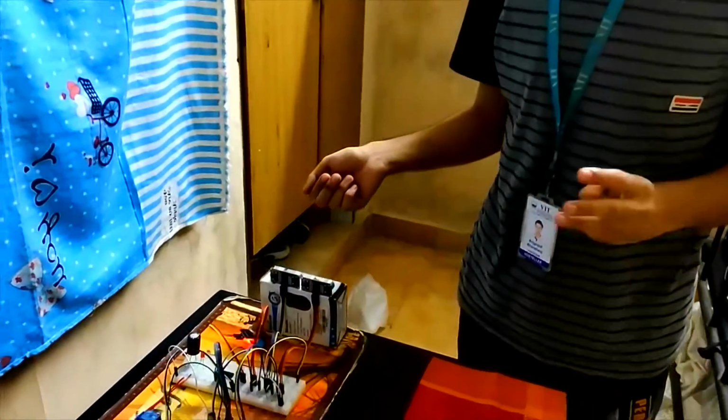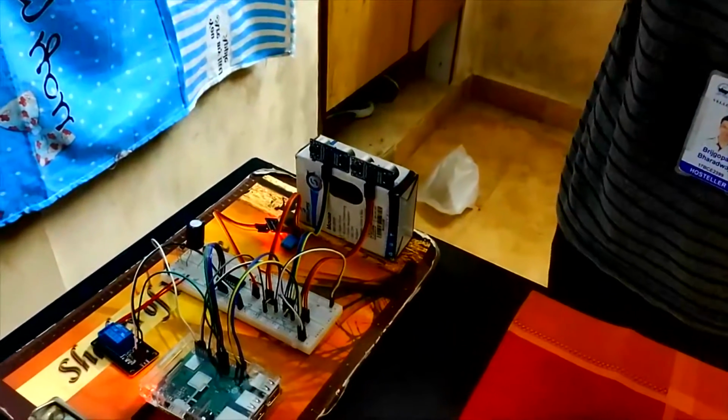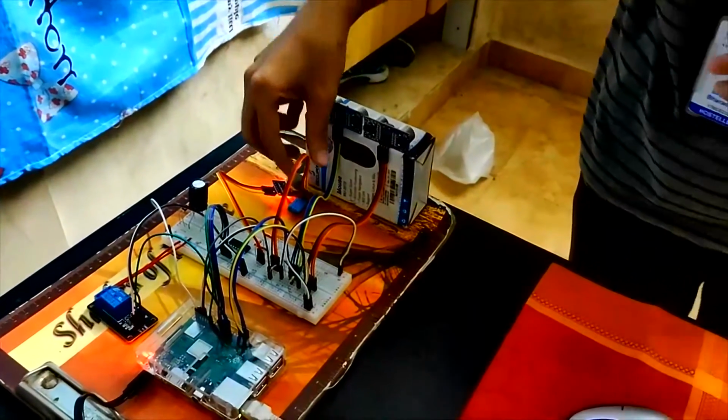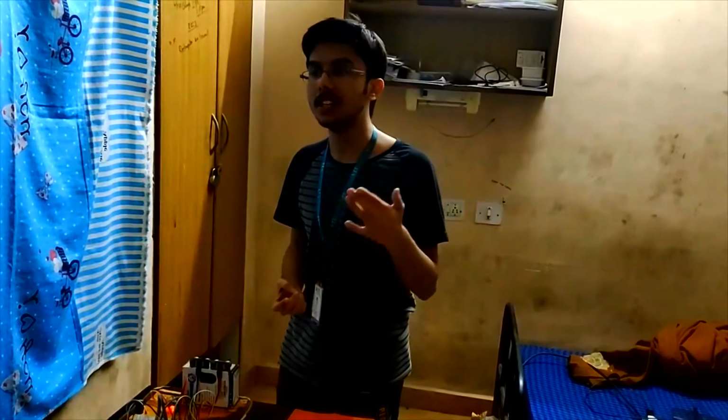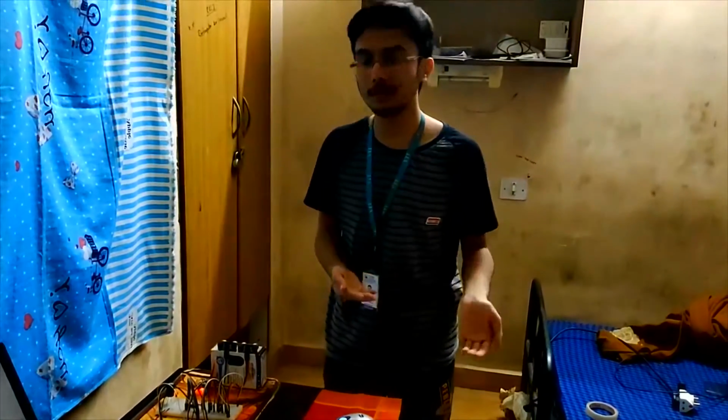The third part that is offered by our circuit is the DHT11 room sensor. This sensor is recording the data related to the temperature and humidity of each individual room present in our house. Now, why is that data useful? If there are some smart appliances in the house, then these devices can communicate with our system to use these values to incorporate some other smart behaviors in their own systems. For example, the air conditioners or the other appliances that are installed in the house can determine whether or not to operate based on this data.